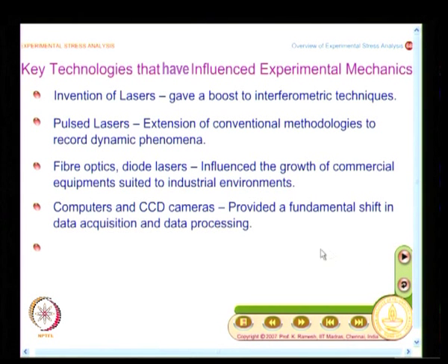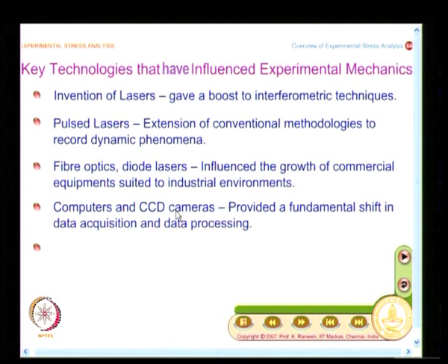And all the optical techniques, if you really look at the development of image processing, earlier they had used a lathe bed on which they would put a photograph, and on the tool post they would have an optical sensor which would pick out the information, and the whole thing would traverse, and that is how they digitized. Digitization itself may take several hours. Then you go to the computer and do extraction of features, other things people have done. Now you have charge coupled device cameras, you instantly get the digitized information.